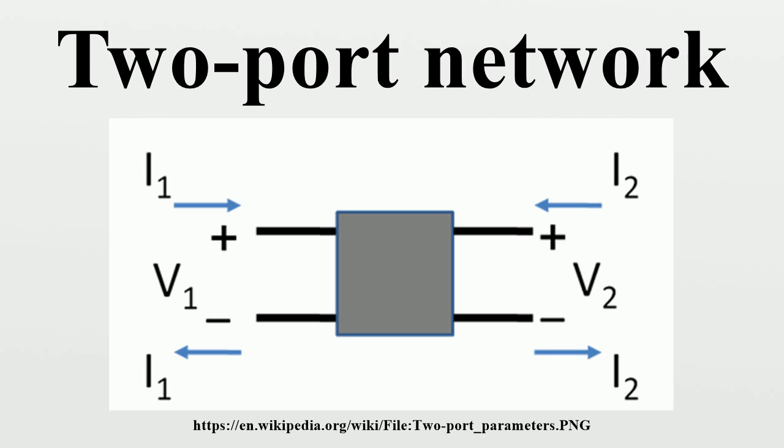For example, consider impedance parameters. Connecting a load ZL onto port 2 effectively adds the constraint. The negative sign is because the positive direction for I2 is directed into the two-port instead of into the load. The augmented equations become as follows. The second equation can be easily solved for I2 as a function of I1, and that expression can replace I2 in the first equation, leaving V1 as a function of I1. So, in effect, I1 sees an input impedance, and the two-port's effect on the input circuit has been effectively collapsed down to a one-port, i.e., a simple two-terminal impedance.